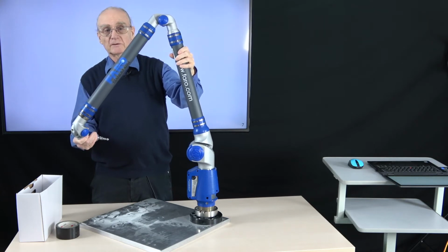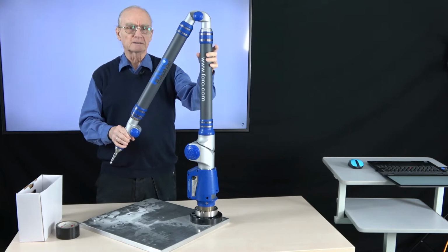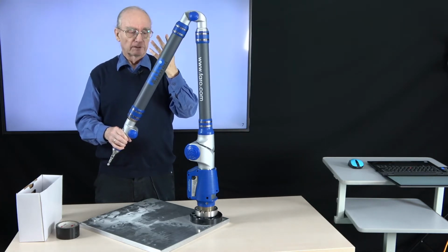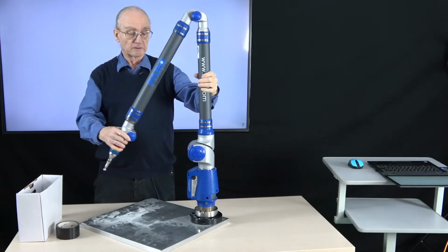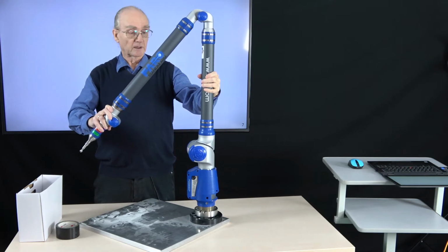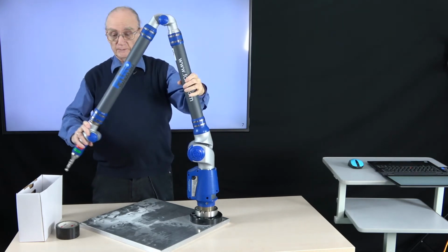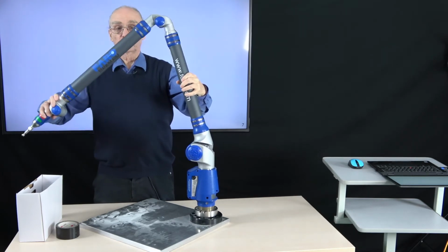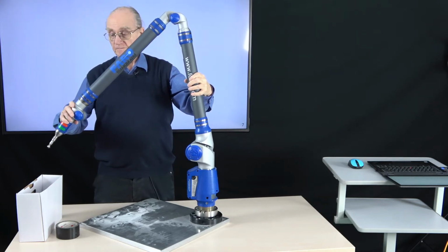Now, why do we have 6? Actually, if we would have 3D coordinates, 3 coordinates, we only would need 3. But if we do this, we are very limited. Let's assume we are only in this plane, and let's assume we have only 2 degrees of freedom. That means this one and this one. Then we can reach only a small area. So it is good to have a third rotation in this direction.